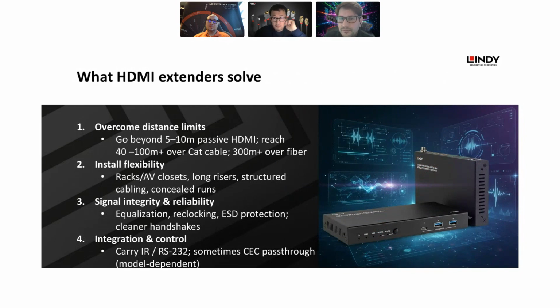What HDMI standards solve? First point, overcome distance limits. Go beyond the 5 to 10 meters of a basic HDMI cable, and reach from 40 meters to 100 meters or more over CAT cable, and more than 300 meters over a fiber cable.